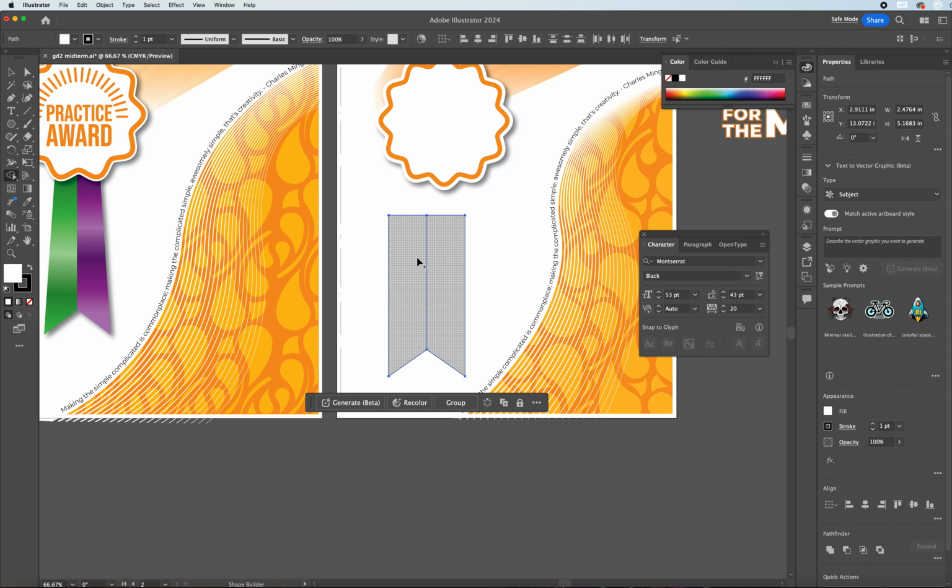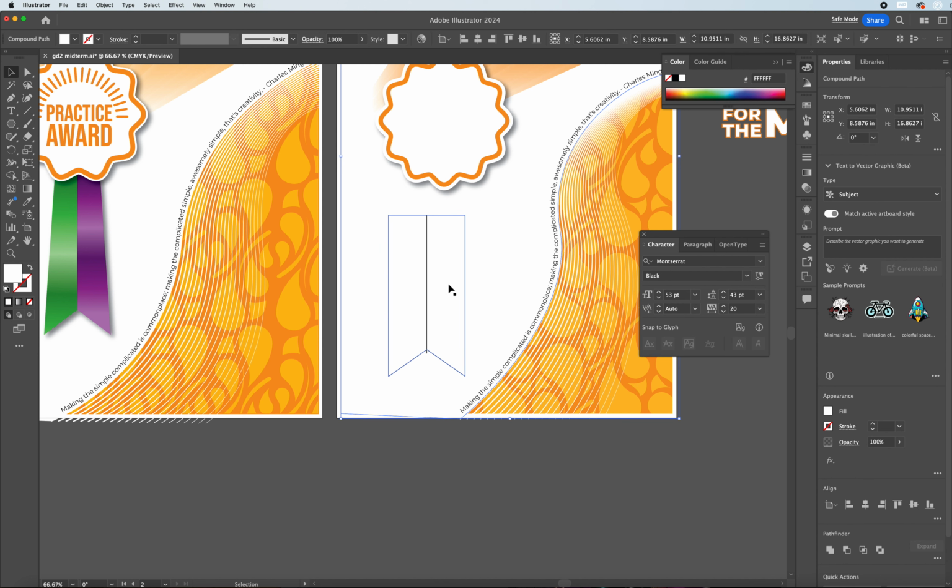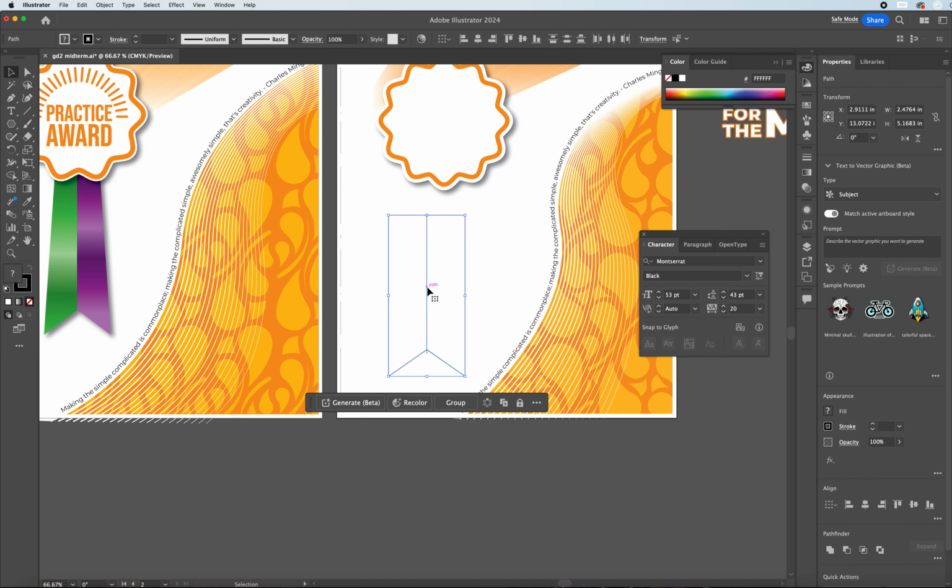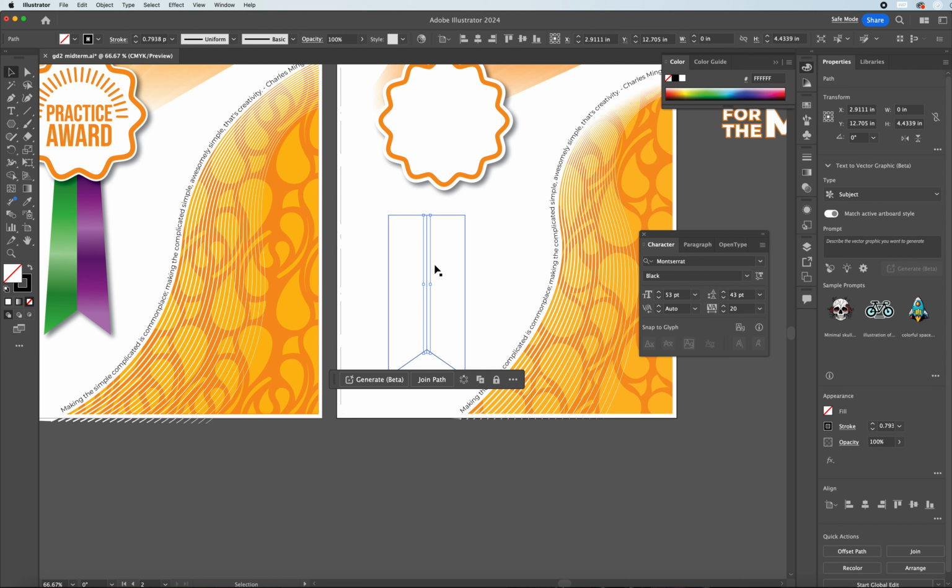So I'm going to click on just this line individually in the middle and look to pull this anchor point so it intersects with our shape. If it extends off of it, we can easily fix it, but I'm going to select on the shape, select on the line in the middle, select on the cut rectangle, and then again use the shape builder.